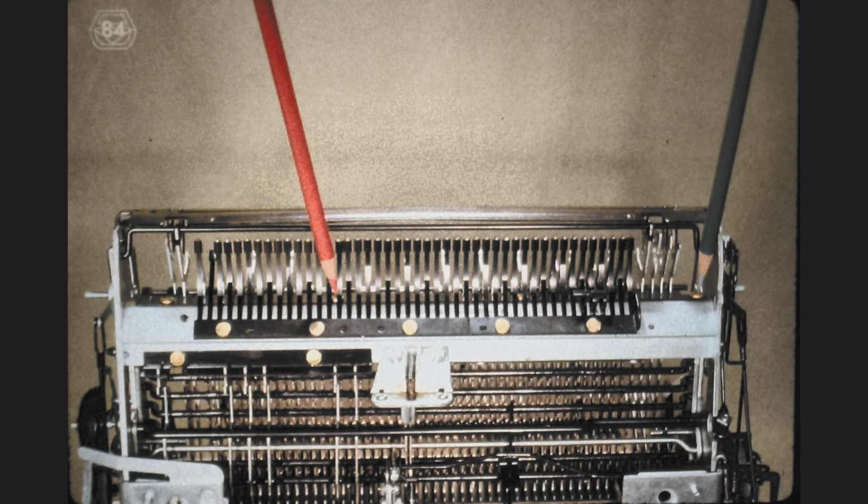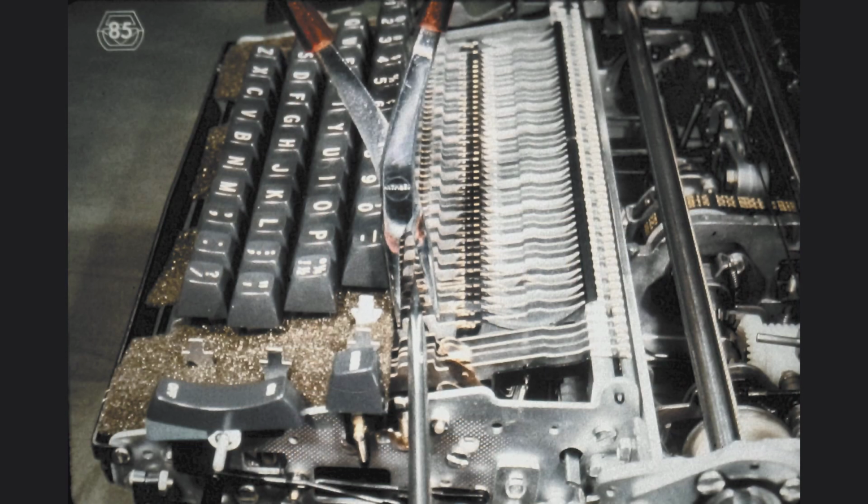At this time, you should perform the described adjustment of 0.5 mm distance between the keylever pawl and the upper lug of the interposers. We equalize the keylever pawl adjustment by individually adjusting those keylevers, which are too far off from 0.5 mm. Notice that we have placed the thick screwdriver shank between the ends of the horseshoe, which is being closed.